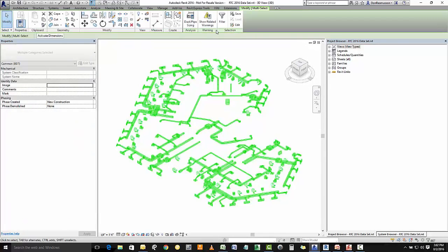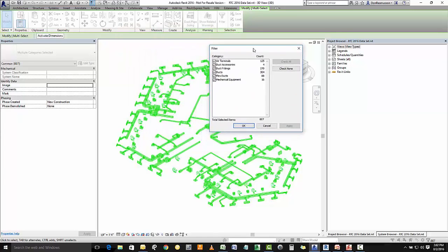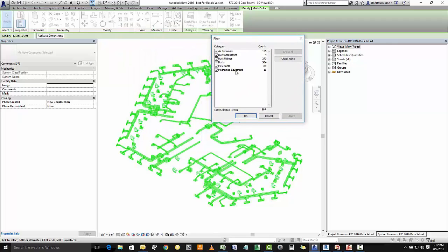Then come to your filter tools. And basically we've got two levels of exports that we have to do. We have to do design line exports and element exports. Now, if I'm going to do a design line export like I'm doing right now, I have to keep in mind that all this export on this RIF file has to be mapped inside of Fabrication CAD, which we'll get to in just a moment.